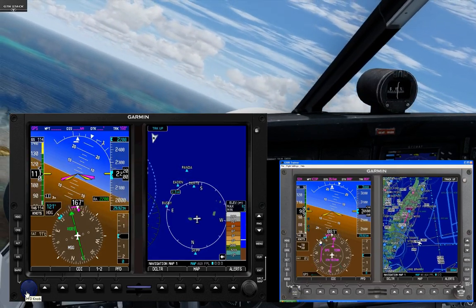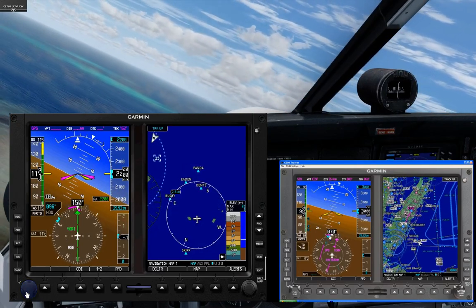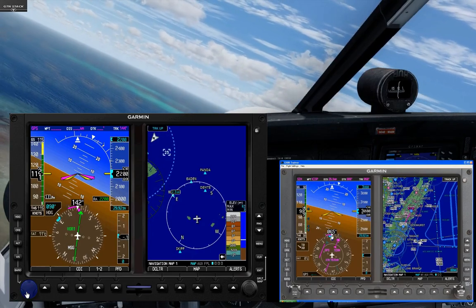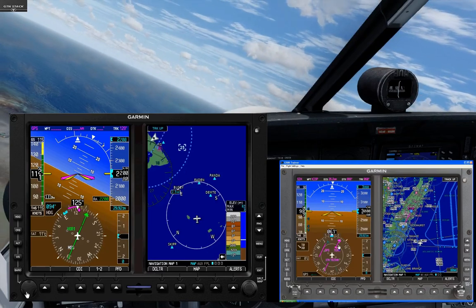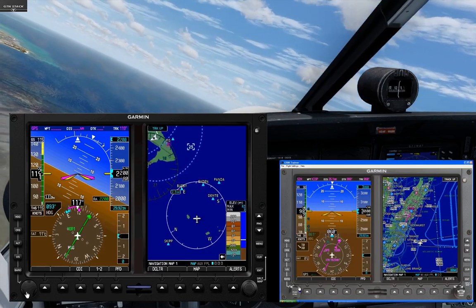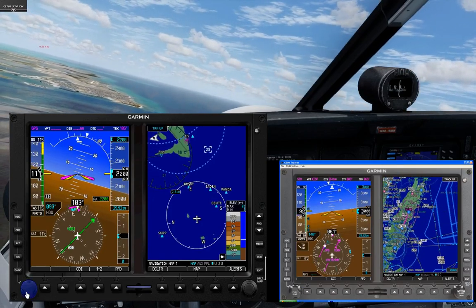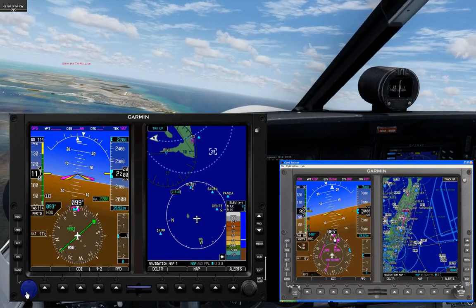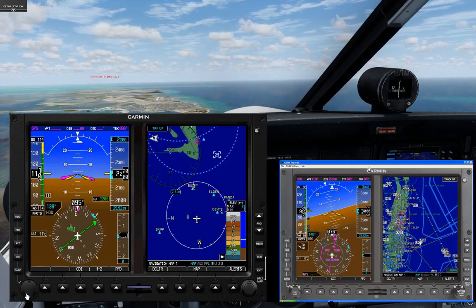So we'll let the aircraft level out on 060. As it does, that trend vector will disappear back behind the center pointer for our heading indication. And now I will start a right-hand turn, and we will see that trend vector once again present itself, slowly stabilize to a standard rate turn.